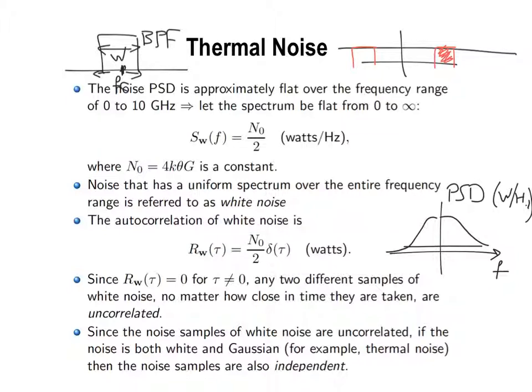So Doctor, do you mean that theoretically, if we are using a receiver that receives all frequencies, it will burn maybe? It will saturate. It will not burn, because in the end the power comes from the source you have, and the power coming from the air is really small. But the problem is your amplifiers will be overwhelmed by the power of noise as compared to the power of the signal that you are interested in. So they will saturate at the noise value and that's it, because they will have more power of noise as compared to the signal.